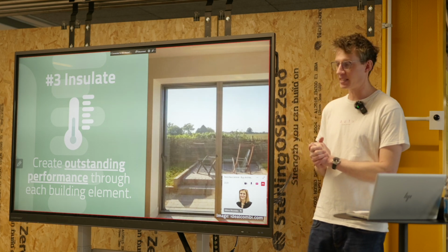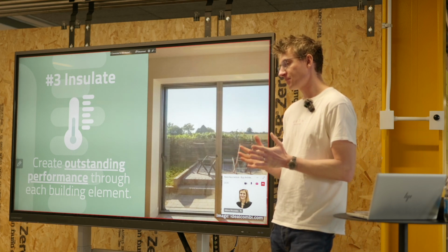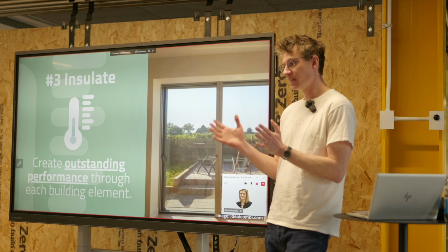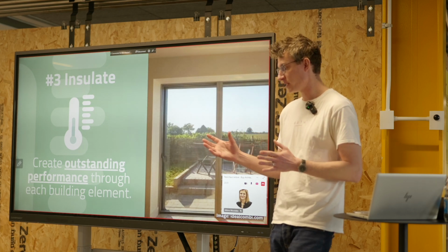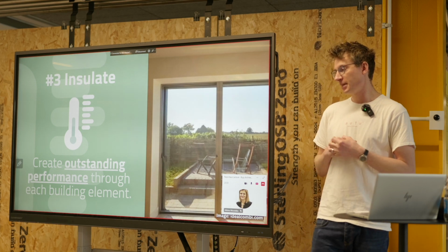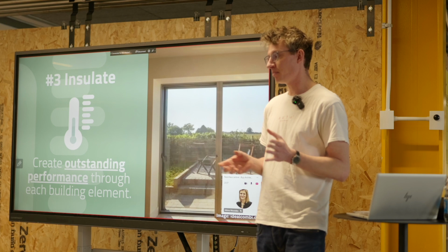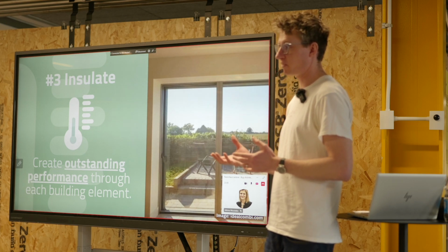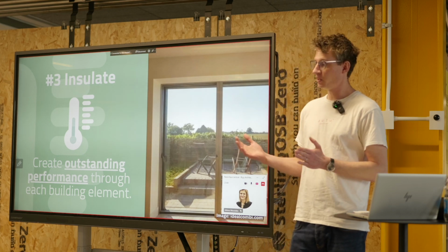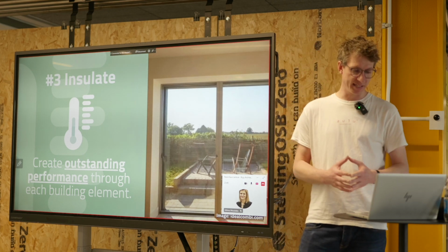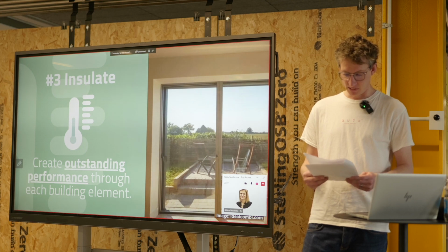I think it's fair to say most passive houses are probably highly insulated timber frames, which are then lined, internally or externally, with additional insulation to prevent cold bridges through the fabric. If you are building a passive house which is more traditional with bricks and blocks, then your cavities might increase from 150 up to 250 basically. So you've got to bear these things in mind when you're designing a passive house from an early stage.